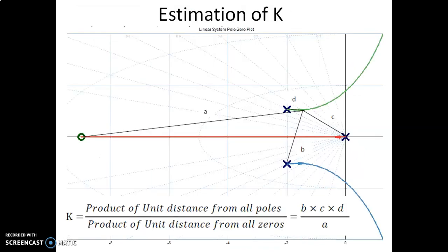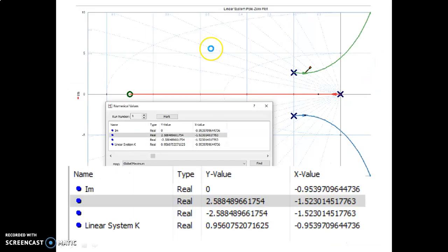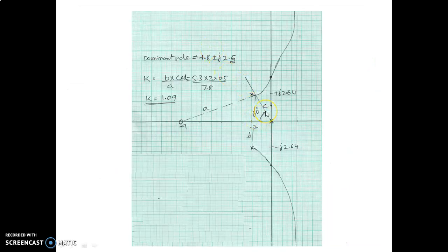For this given problem, we first plot the root locus and then draw a line corresponding to 60 degrees. This is that 60 degree line, which corresponds exactly to 0.5 in the 20-sim simulator. Otherwise, we draw a line corresponding to 60 degrees, and this is the point of intersection of that line with the root locus. Then you join all the zeros and poles to this point.